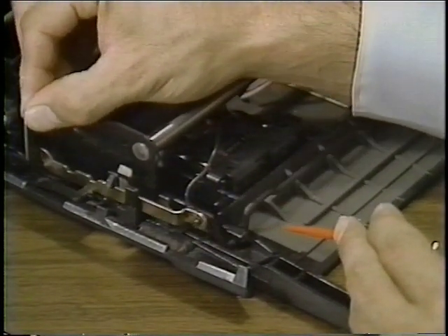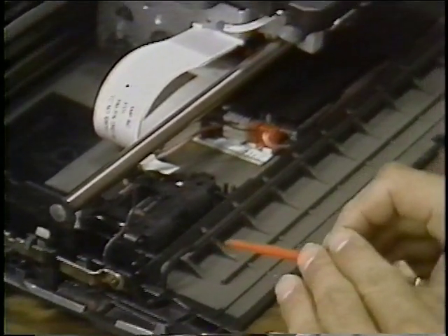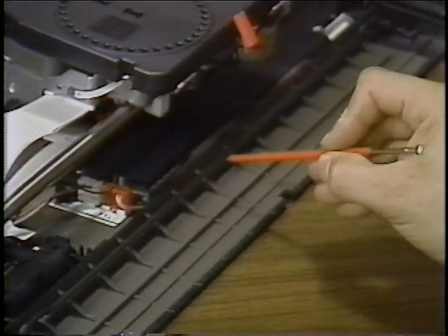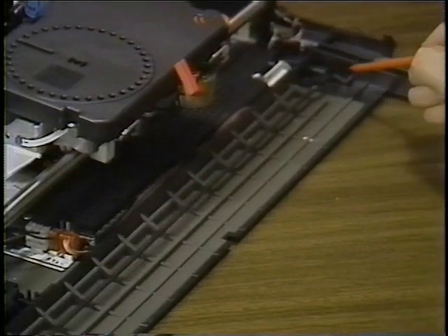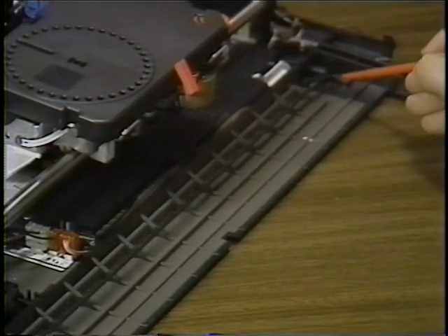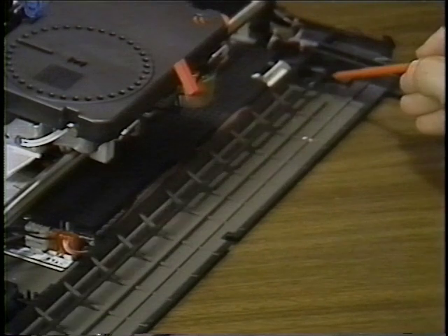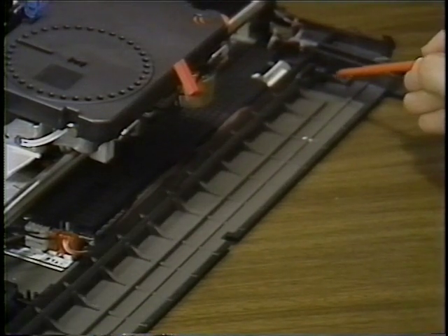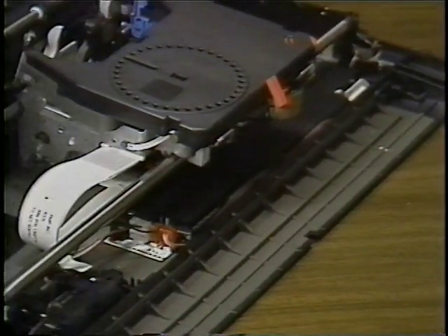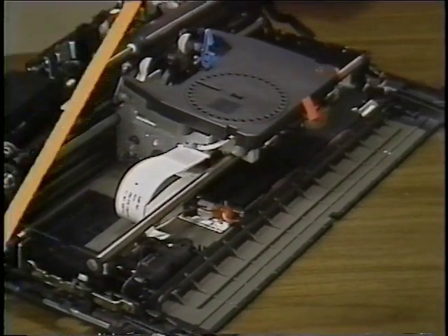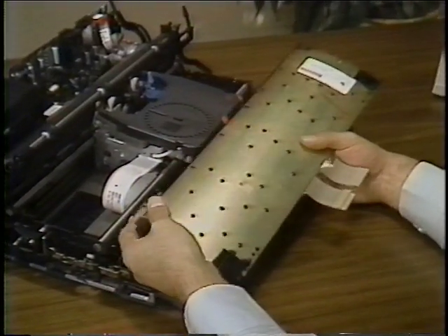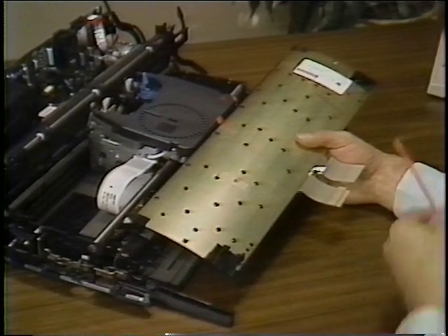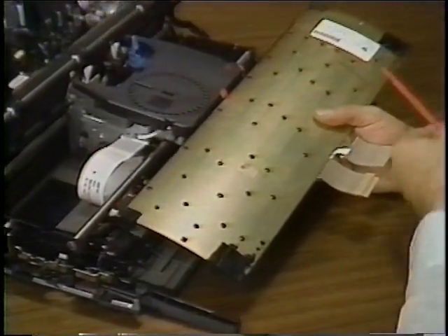As the keyboard adjust lever moves to the rear, the adjusting bail rotates to the rear. Notice that there is a high point at each end of the bail. The high points on the keyboard adjusting bail fit into these camming surfaces on the keyboard mounting brackets.